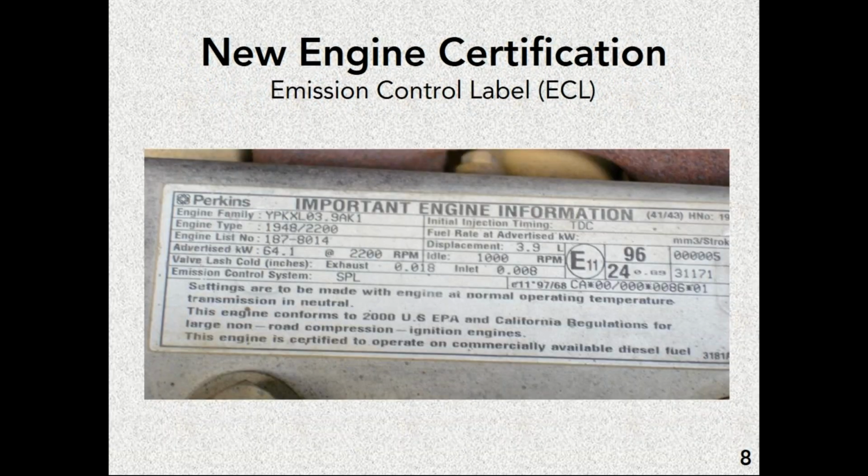You can get some of the same information from the engine tag itself. This is what's called an emission control label. When the federal government certifies new engines for sale in the United States, one of the things that they require manufacturers to do is to place a label with the certification information somewhere on the engine itself. This label will have all the information related to the model year of the engine family, the standards that it meets, and a whole lot of air pollution related information.